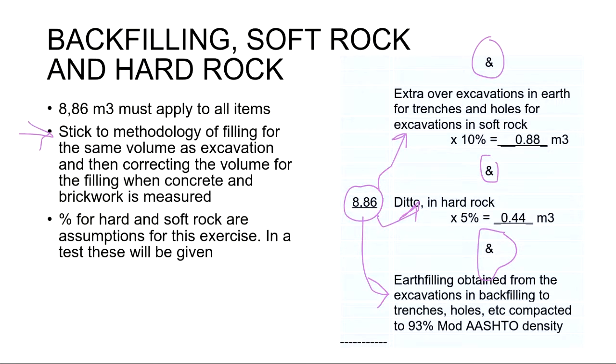So here where we have many walls intersecting with each other, and each one of them in the collections has been adjusted according to the width of their foundation walls and the adjustment for their concrete, we don't have to worry about the little anomalies on the ends and the connections, because we're going to use the correct lengths from our collections to do the correct measures when we do the foundation walls.